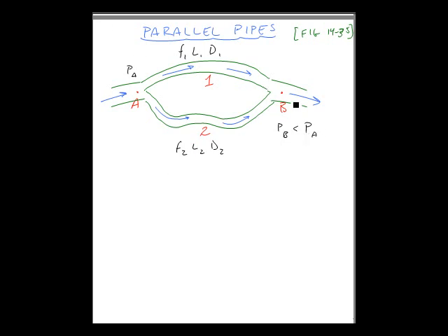In order for these two lines to come back together and actually flow in this direction, without this being a total branched flow, if this is not pressurized, the head loss for 1 has to equal the head loss for 2. So the losses through 1 have to equal the losses through 2. And on a similar note, my volumetric flow rate at point A has to equal the volumetric flow rate for path 1 plus the volumetric flow rate for path 2 because of continuity. And this goes back to incompressible, sorry, is equal to volumetric flow rate B.